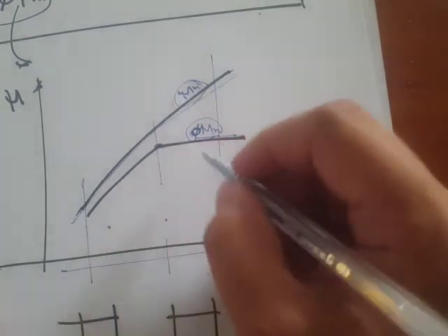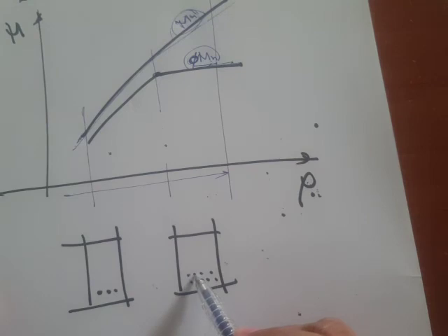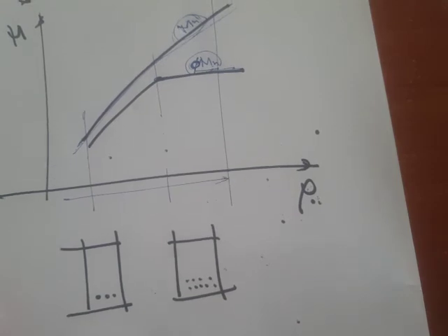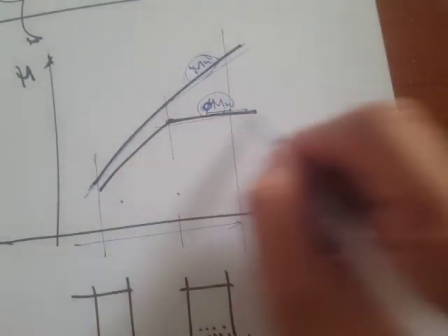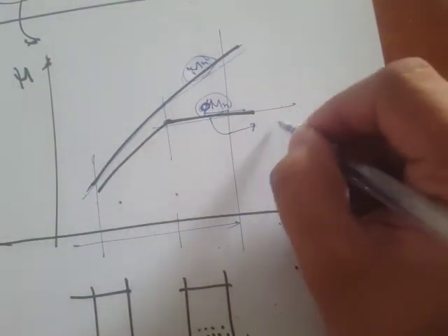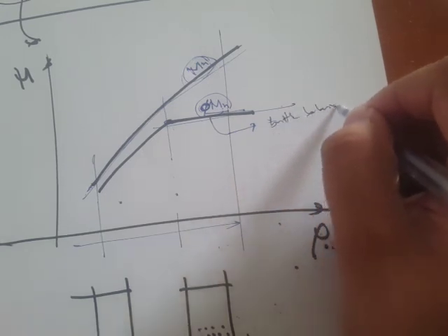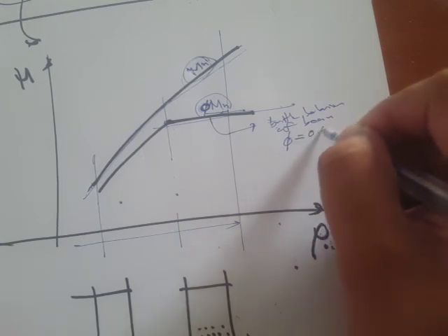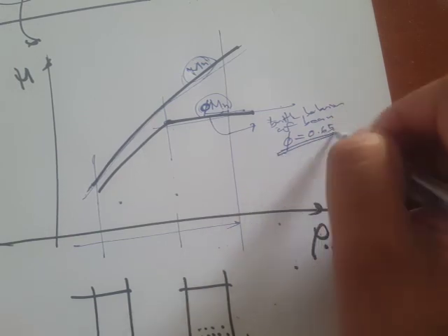It's simply because the more you increase the percentage of steel, you're getting into a brittle mode of failure, or brittle behavior of the beam, and hence your reduction factor is 0.65 instead of 0.9. So that's the reason.